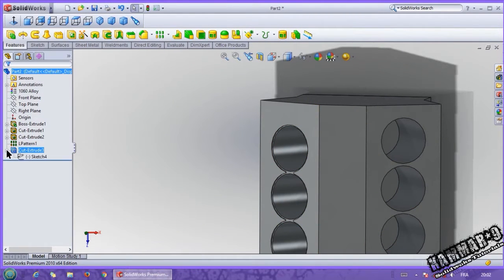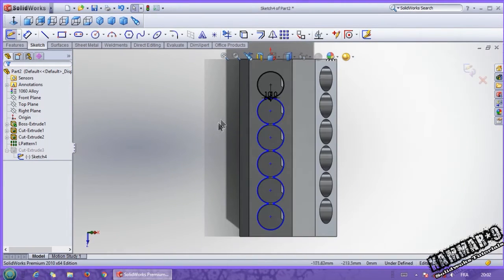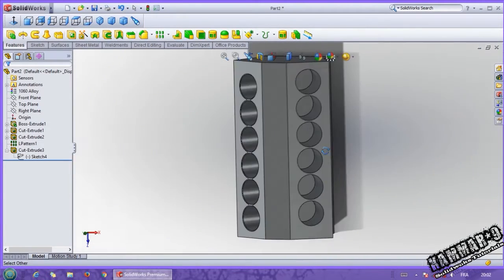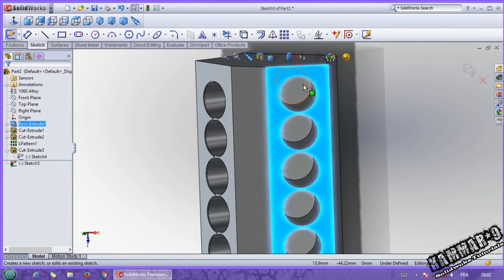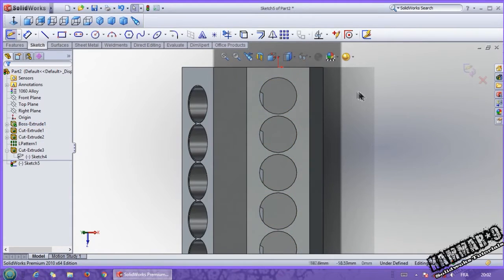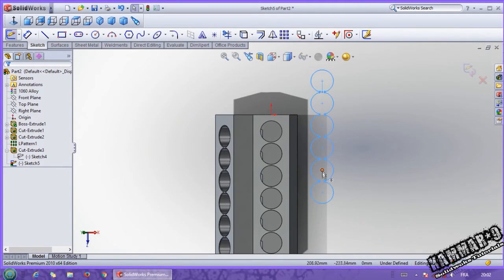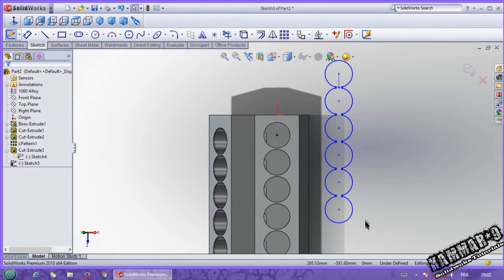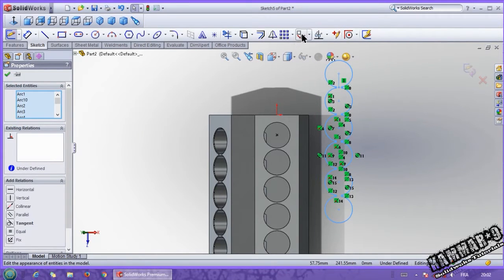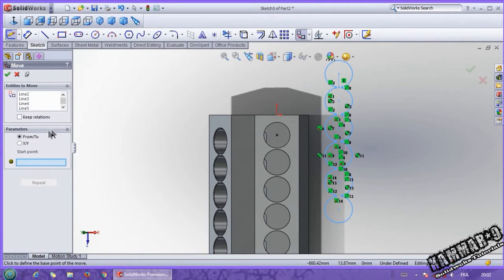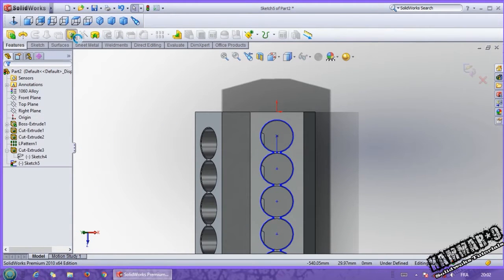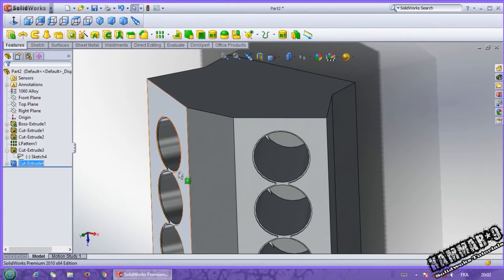To repeat that, I can copy this one, edit your sketch, copy this, Ctrl and C with your keyboard, validate from here and go to this one, go to sketch, and you can click here and Ctrl V to paste it, I think. Then put a point here, then select all of these, copy or move entity from here to here. Click OK and make the same thing with 2 mm here, validate.